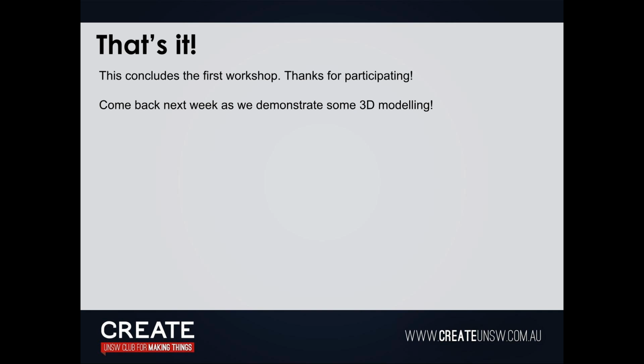You got your scale. So if we want to do like 4, yeah, it's pretty big. It takes up the whole page pretty much. We'll do 3, right? And it'll change into 2D, right? There's also section views. So if you want to select your parent view, for example, if you want to see the inside of that and that. Oops, sorry, I messed that up. I should know better than this. Yeah, so if you want to see a section of that, specify a start point. And then roughly there. I think that should do it, right?